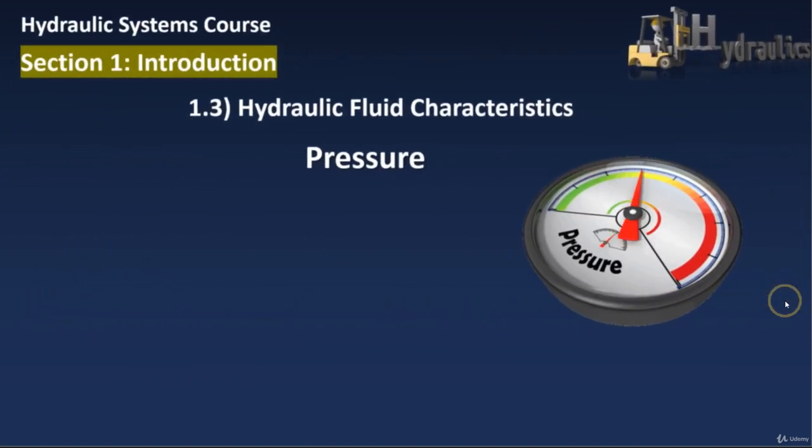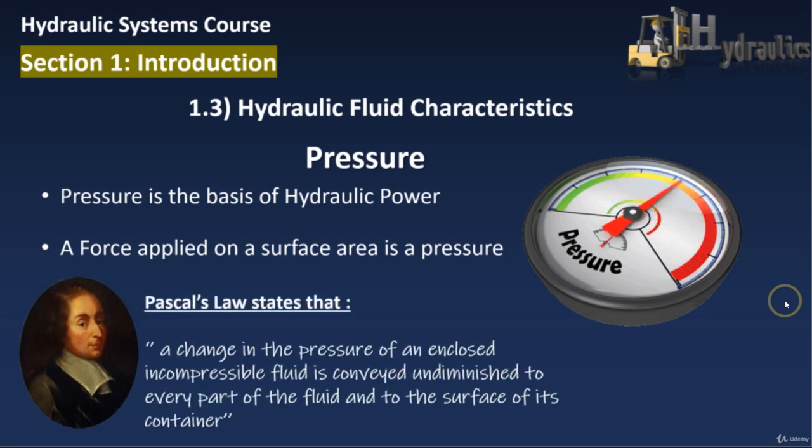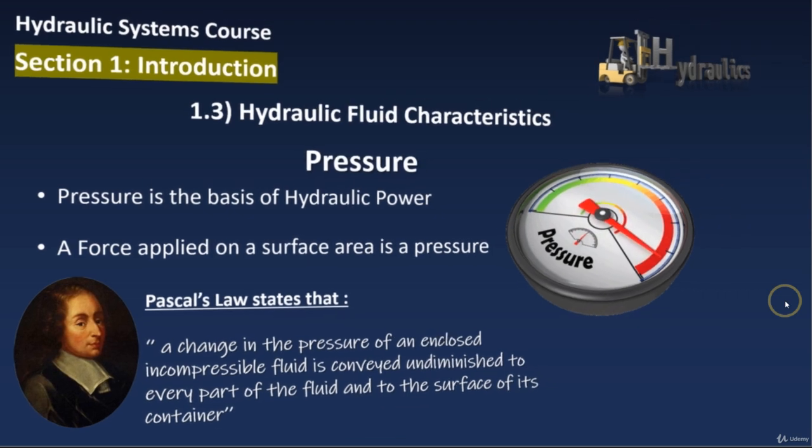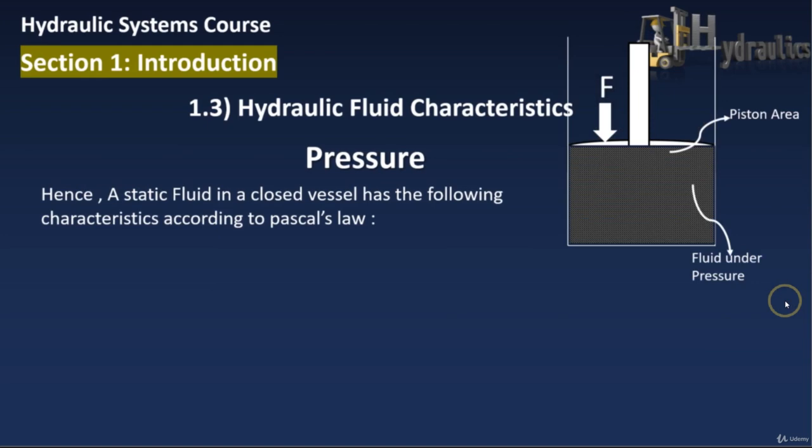Pressure is the basis of any hydraulic power, and a force applied on a surface area is called the pressure. If we recall our previous studies, Pascal's law states that a change in the pressure of an enclosed incompressible fluid is conveyed undiminished to every part of the fluid and to the surface of its container. Hence, a static fluid in a closed vessel has the following characteristics according to Pascal's law.